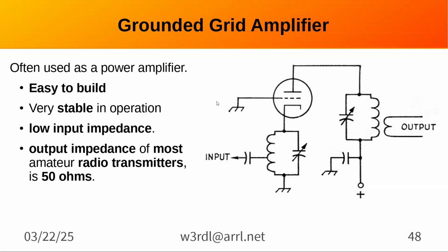So it's going to give you a very low input impedance and you're eventually going to match a 50 ohm output impedance. And you notice it's a step down transformer as shown because my Ameritron runs about 1600 volts, I think. It puts out 800 watts. So I'm not sure what that output voltage is, but it's probably only a couple hundred volts, if that.